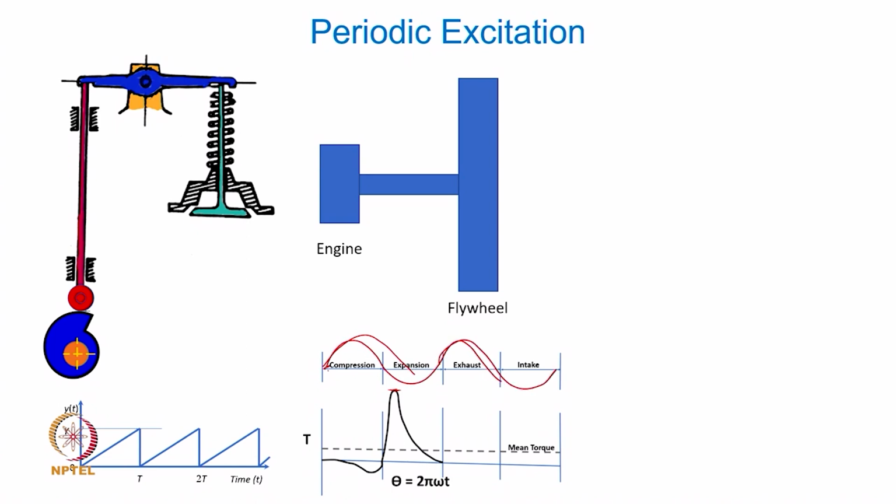So, if this is not the case and the torque as a function of time cannot be expressed as a harmonic time function, I will have to figure out how to find the response theta t. That is what we are trying to find out, the angular or dynamic twist in the crankshaft. Given certain speed and operating conditions and the torque being generated at the engine, what is the maximum twist the crankshaft is going to be subjected to, and whether that